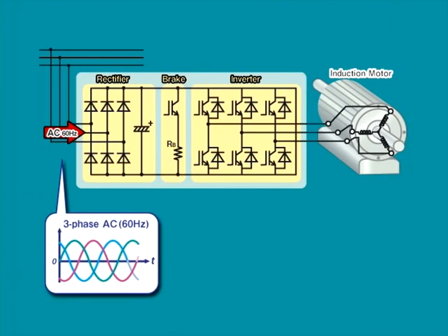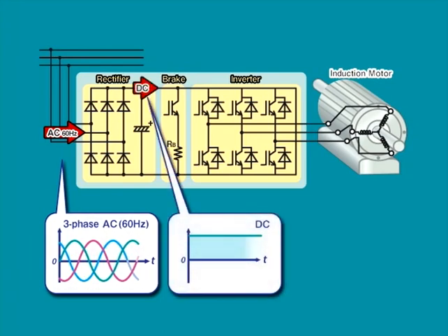The electric motor on a ship is operated by 60 Hz AC voltage, and if the load does not change, it rotates at a constant speed. The revolution speed of the electric motor can be controlled by voltage and frequency. Therefore, the inverter allows for precise control of the motor's revolution speed. Power is input as DC voltage, which is obtained by converting three-phase voltage to DC voltage via the diode rectifier circuit. Even though the inverter is used in combination with the rectifier, the system is often referred to simply as the inverter.